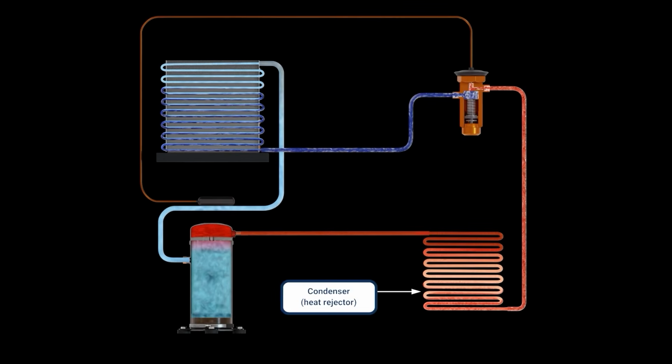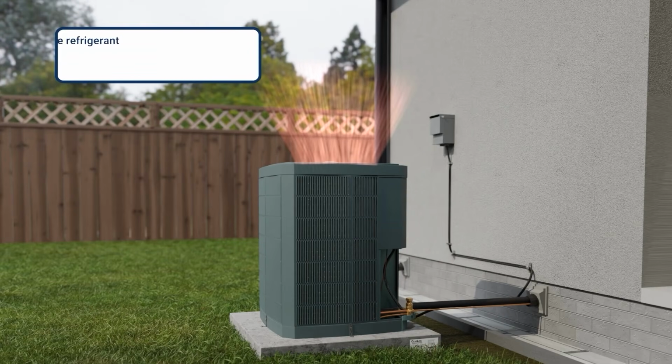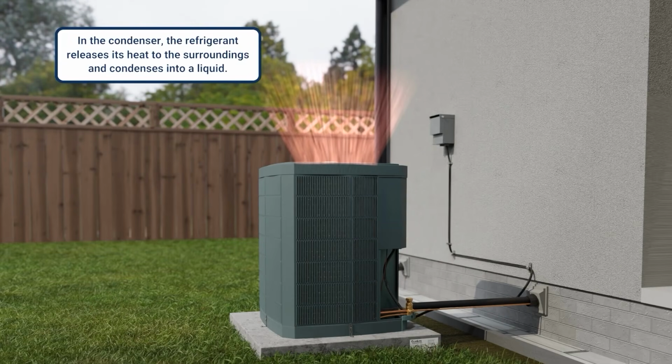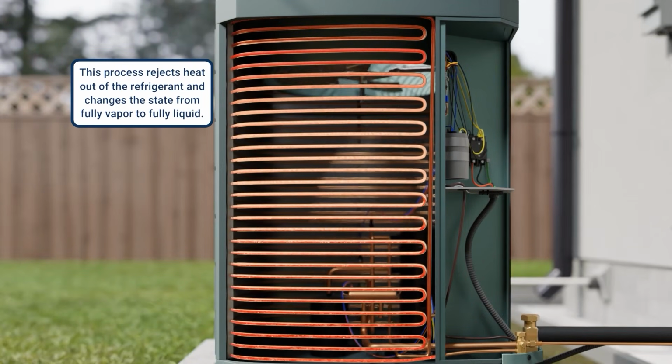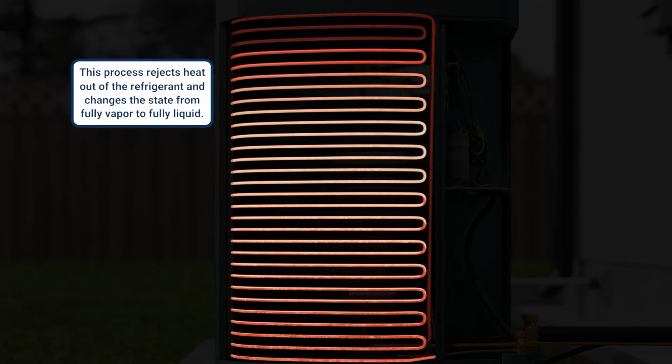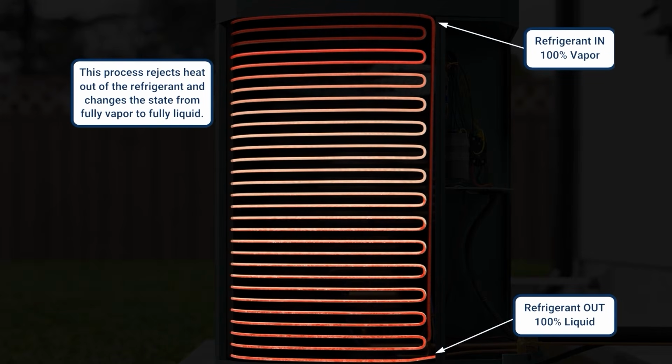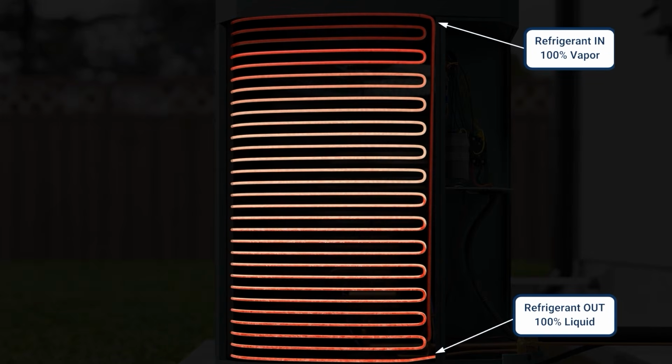Talk a little bit about the condenser. We talked about this yesterday, and it's just a quick refresher. Vapor comes out of our compressor. It goes into the top of our condenser coil as fully vapor. The first little bit, it's dropping temperature fast. It might go 210, 205. It's dropping until it hits that condensing temperature.